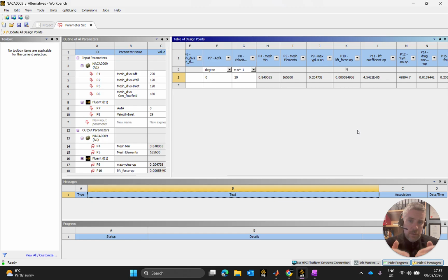Now, yes, we are looking at a couple of different airfoils, and you say, well, why don't we compare them parameters from airfoil to airfoil? And normally you would. However, in our application for STEM racing, lift coefficient and indeed lift force is not really something that I should concern myself with, because if anything, it should be negligible. It shouldn't be there at all, but like, we're never going to get a zero lift force, let's face it, on this. It will be there, but it should be, for all intents and purposes, zero. It is not lift that we're really looking to achieve in our STEM racing setup for our car, albeit a wee bit of lift, as I've always said, does not hurt once it is lift and not downforce.